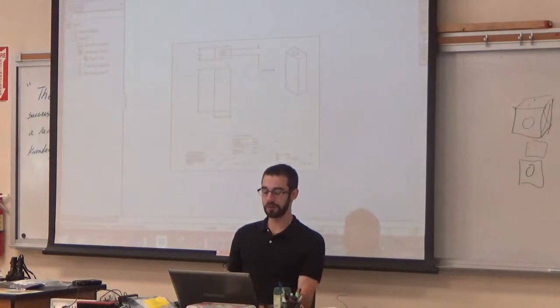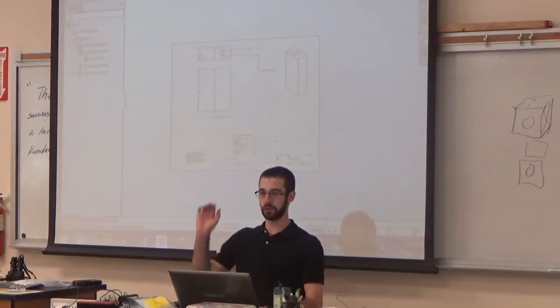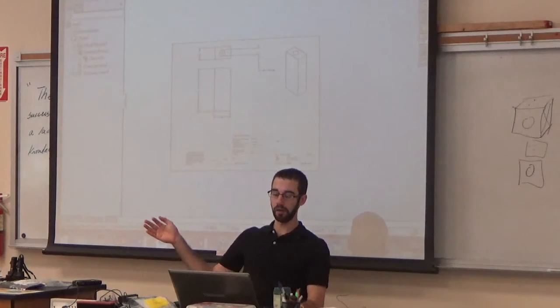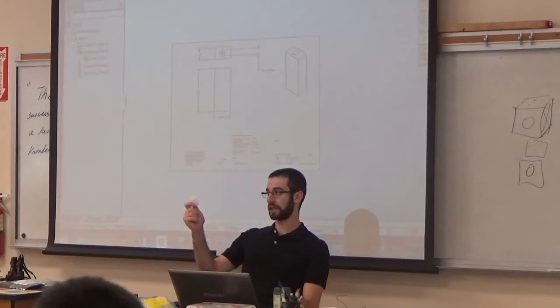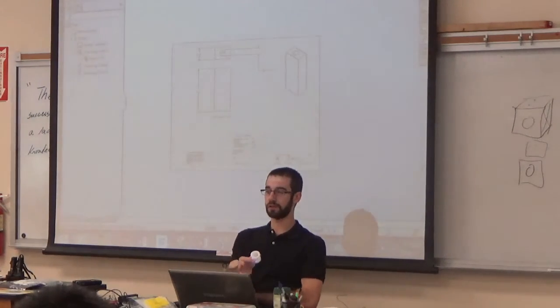Yeah, so remember, drawings are a communication method. And so in this day and age, when you talk with a vendor, you're going to be sending both the drawing and your 3D CAD. But part of the drawing came back from when we didn't have computers to do the 3D CAD. It also allows us to say that even though the part looks the same, it's not the same if you incorporate the tolerancing.